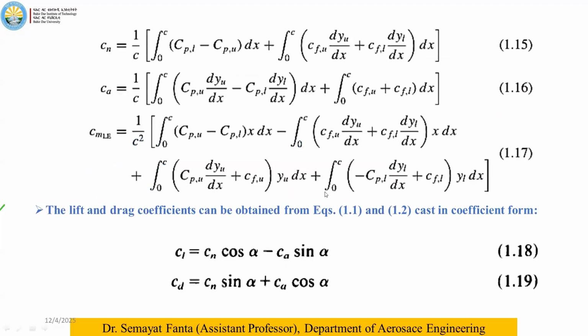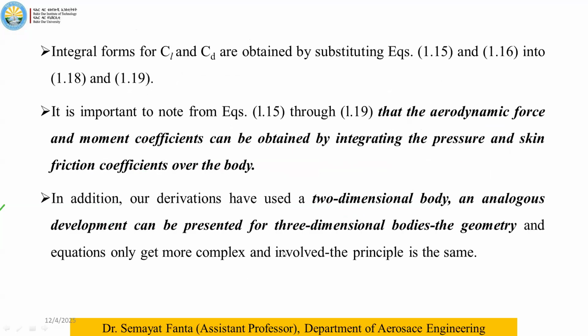Okay, so once we get CL and CD, those are our important coefficients. So we can directly calculate the lift and drag of the aerofoil. The lift and drag of the aerofoil are not directly equal to the lift and drag of the three-dimensional wing.